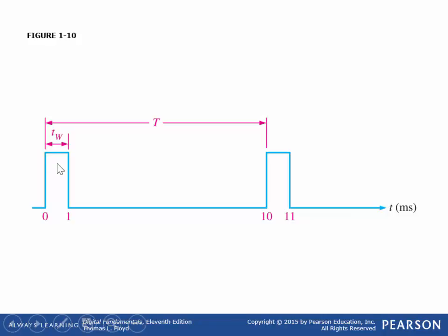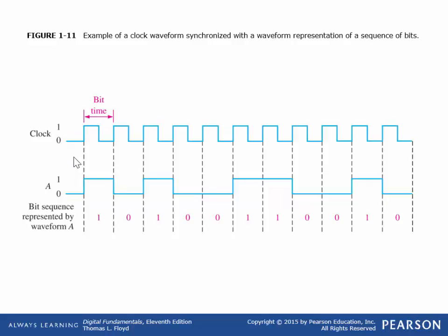Here we're looking at about a 10% duty cycle. The period is 10 milliseconds and it's on for 1 millisecond, so that's a 10% duty cycle. As I widen the pulse width, I can go to 50% duty cycle, and my light is going to get brighter. This is quite often used to brighten and dim things such as LED lights. It doesn't work for incandescent lights. These are fluorescents. You can't dim fluorescents typically. So then we've got some.